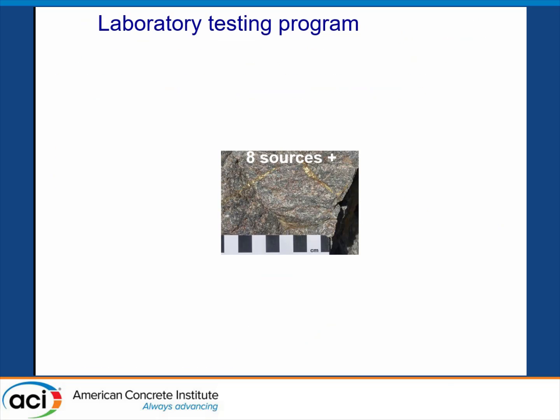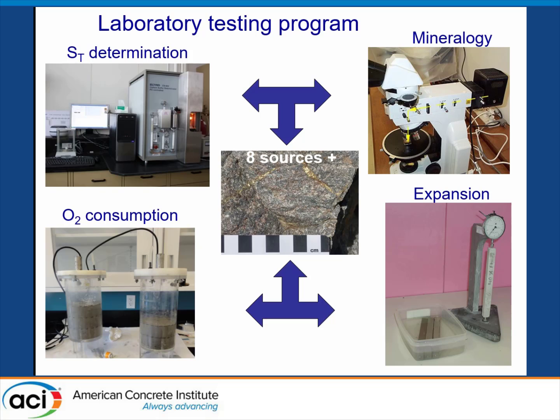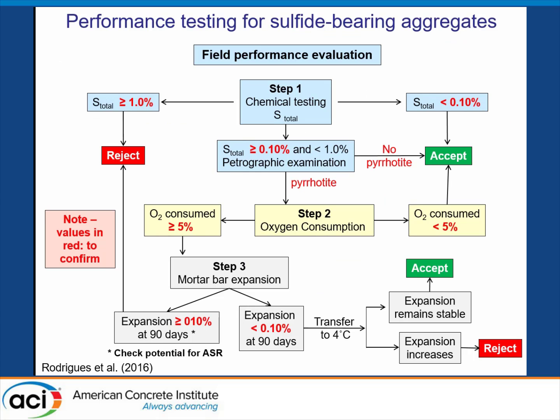And we've done a large laboratory testing program with 8 different sources of aggregate. We measure the total sulfide determination. We evaluate the mineralogy with petrography. We had an oxygen consumption test and an expansion test. I will just show you the main results of all these test programs.